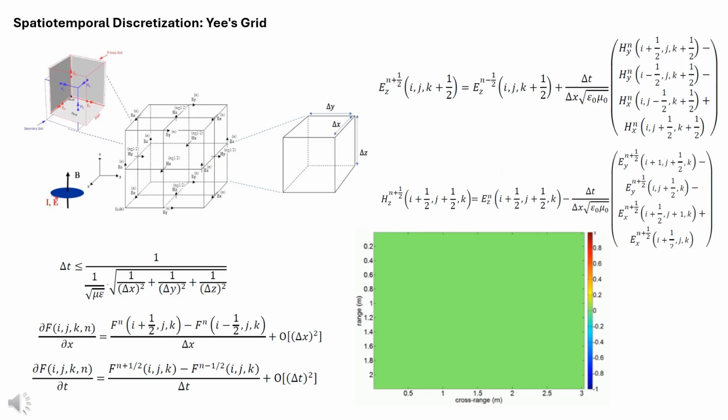For handling non-uniform geometries, 3 approaches are considered. First, shifting the geometry may lead to errors due to misalignment. Second, minimizing cell size requires more memory and computational power but provides finer resolution. And third, non-uniform cells, the staircasing method. This approach approximates curved geometries with staircase cells, offering a flexible transition between boundaries while reducing memory and computational requirements.